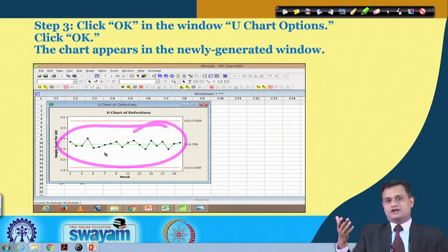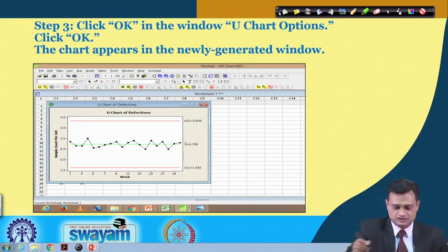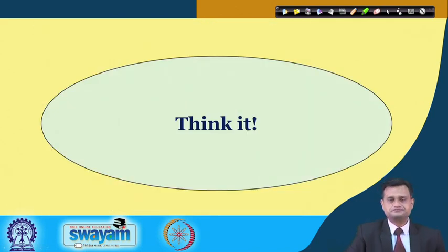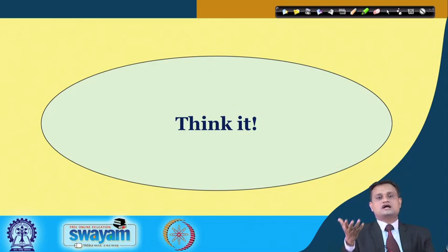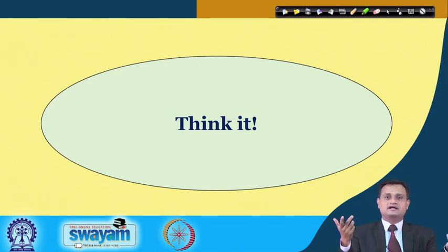unless you observe a typical pattern which is an indication of some assignable cause. Otherwise, if the points are falling well within the control limits, you say that you have the process within statistical control. Once this is done, you can establish control over your process by taking the appropriate step for removal of the assignable cause. If you are in the initial stage trying to set up the trial control limits, then let your control limits stabilize. Use this control chart as a gauge to monitor your process continuously for a given quality characteristic, and whenever a point falls outside, you must investigate and take the appropriate action.